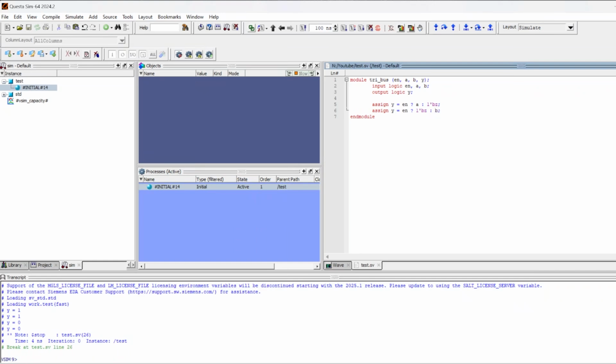So this becomes very important in the context of communication protocols and their design, in which we will be declaring one of these assign statements inside the master and the other one inside the slave. But here, just for the sake of syntax, I will be demonstrating it using the logic data type for Y. So first, let's run the code and check for any compilation error.